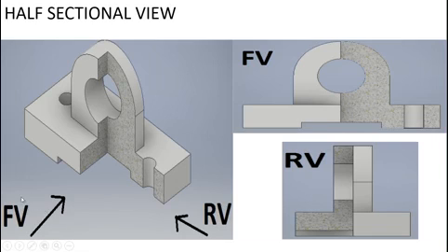So now if you are standing at the front view here, you will see one side of the drawing is smooth, and the other side is a rough surface. Remember, the rough surface is where you have been cutting. So I'm looking at this orthographic view of the same drawing. You can see half of it is still smooth because we cut only half of it, and the other side is a rough one. So we're going to hatch on this rough surface.